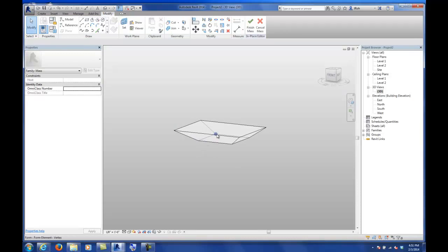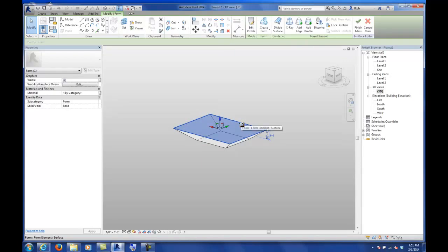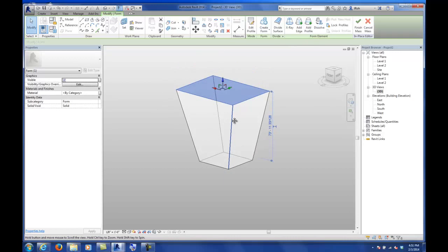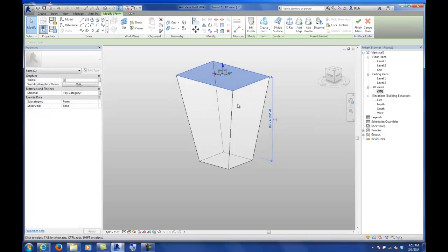At this point, this is where it starts to become intuitive massing. We can tab over different parts of this model. I can tab over until I can only select that top face, and I can push and pull, and it's going to give you at least dimensional data, with those temporary dimensions. So while I'm pushing and pulling, I know that I'm modeling to some sort of scale. If your project requirements are that this mass can only be 50 feet high, maybe I want to be at that height.